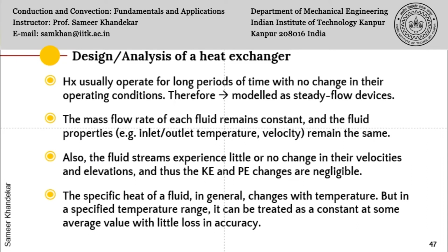Also, you must remember that, let us see under what assumptions we will do this analysis. So there are some major assumptions. The first one, of course, is to note that heat exchangers usually operate for long periods of time with no change in their operating conditions. So more or less, once they are designed, they will continue to operate. Of course, as we have studied in the last lecture, fouling may take place over a period of time and the performance may decrease a bit. But then routine maintenance is done to clean the heat exchanger also.